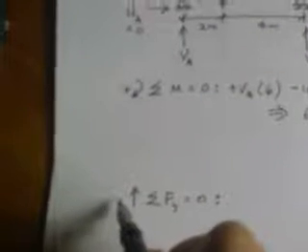Okay, now to determine VC, we can use the second equation there, which is sigma Fy equals 0. Sum of all vertical forces equals 0. So let's just do that here. Sum of all vertical forces equals 0. Put a colon there. Now we use a sign convention that positive is all forces which are going up. All forces going up is positive.